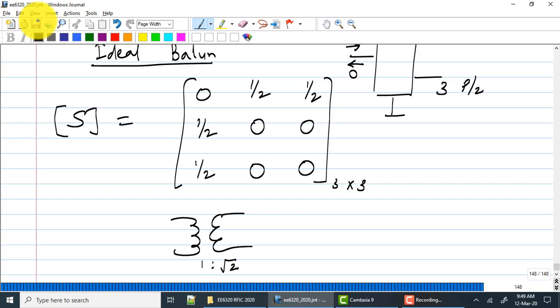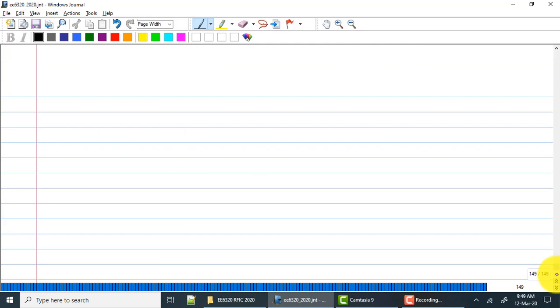Just remember, you are not sure whether your results are correct or not. What does that mean? First I plotted first order and third order, and they are linear with minus 46 dB. Then I plotted IIP values for minus 46, minus 53, and all of them should give the same value. Are you doing a 2-point simulation? You are saying minus 46 and minus 56. No, I did it for minus 46, then again I did for minus. Why don't you just run a sweep? I don't understand this. No, I didn't run the sweep.